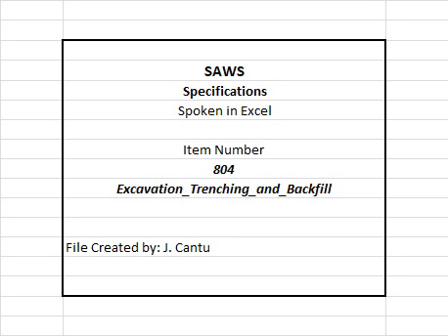C. For pipelines up to 24 inches in diameter, initial backfill material shall be placed in 2 separate lifts above the bedding material the pipe is set on. 1. The first lift shall be spread uniformly and simultaneously on each side and under the bottom quadrant of the pipe to the midpoint or spring line of the pipe.